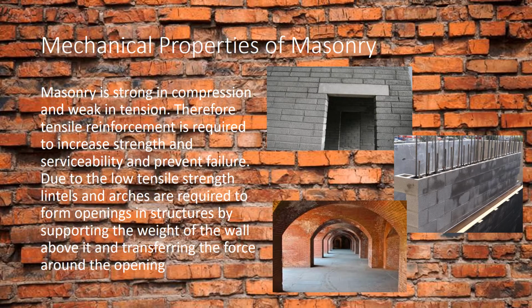Masonry is strong in compression and weak in tension. This means tensile reinforcement is required to increase strength and serviceability and prevent failure. Also, due to the low tensile strength, lintels and arches are required to form openings in structures by supporting the weight of the wall above it and transferring the force around the opening.